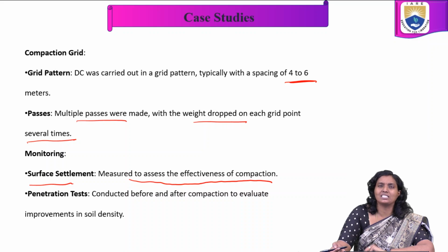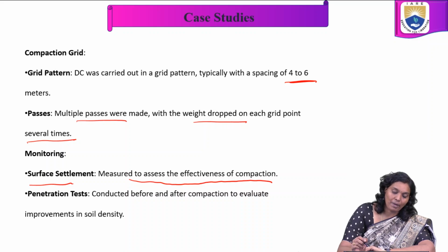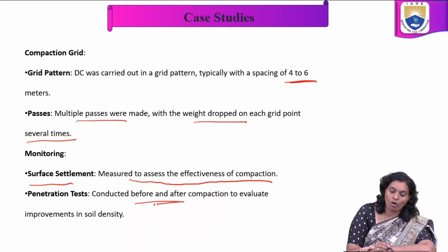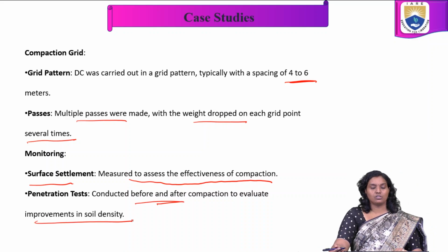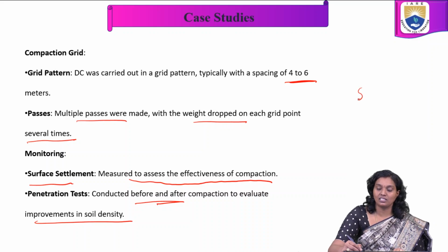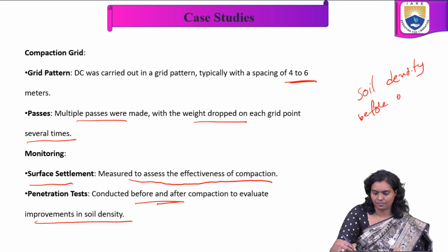A penetration test is conducted before and after the compaction to evaluate the improvement of the soil density. For understanding the soil density and other parameters, we have to conduct the before and after tests.